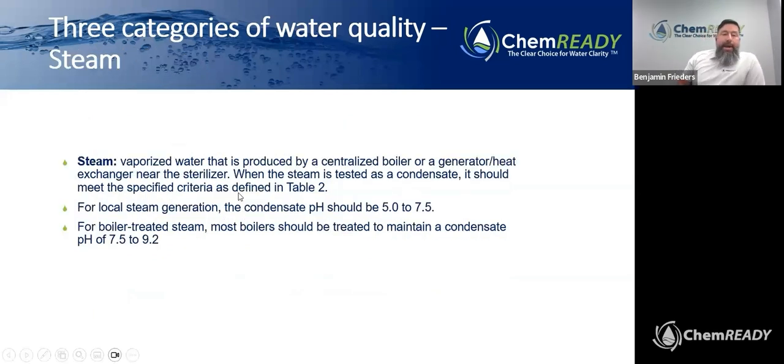And then finally, as I mentioned before, and I had my caveats about steam in terms of AAMI ST108, it is vaporized water that is produced by either a centralized boiler or a generator / heat exchanger near the sterilizer. So it's not the steam inside the sterilizer itself. If it generates its own steam, again, it comes from an external source. The notes here, and we'll talk about the water quality parameters shortly.